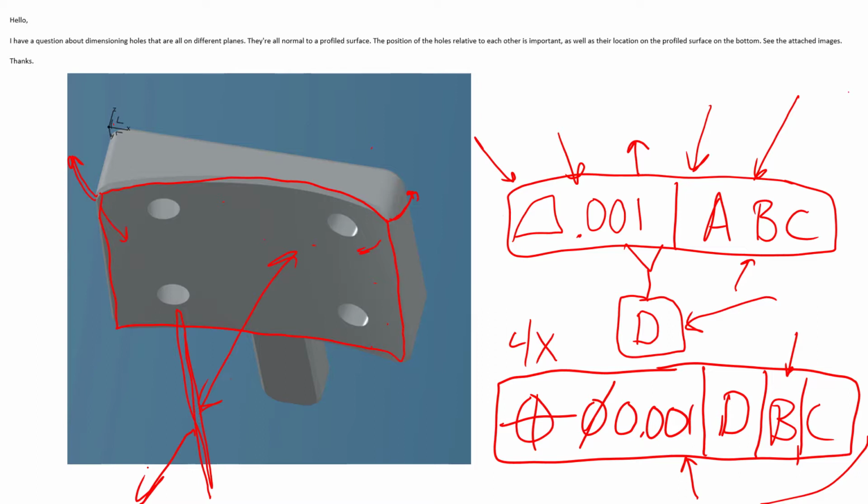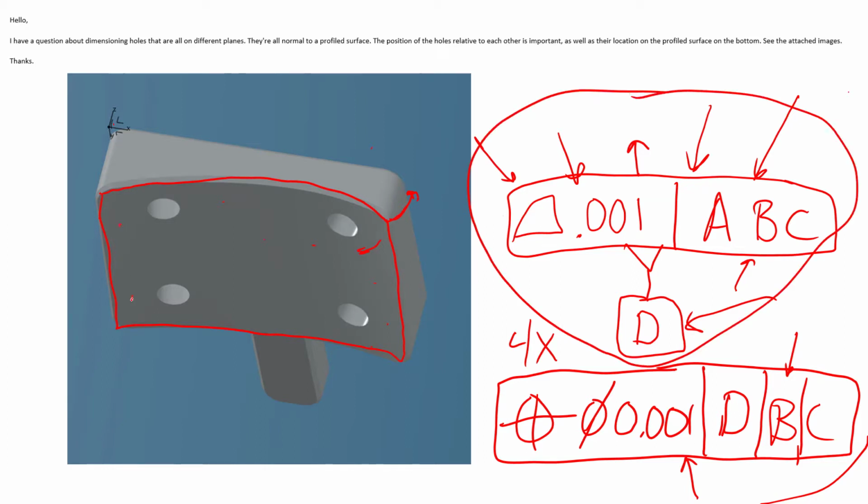You would need something like a laser scanner or a CMM to do this. So if you did have a laser scanner or CMM, what you would do, when you're inspecting this control right here, is tell the CMM that this is the wall of a cylinder and to give you some sort of axis. So it would find the axis out in 3D space. It would then use that axis to do what we talked about before, which is, when you go to inspect those holes, they would have to be perpendicular or normal to the surface and really intersect in that axis. So we'd still do the same thing.